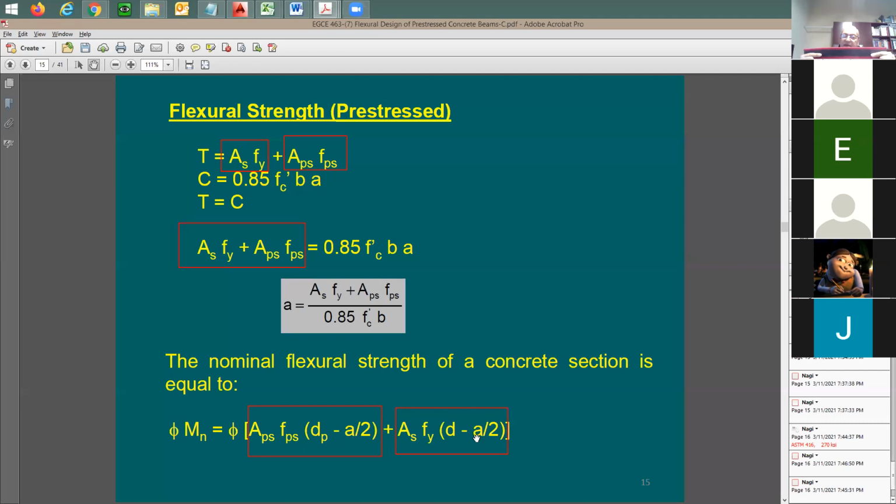So we're going to bring the beam, put it in place, put some conventional rebars, enough to support the self weight of the beam. And then after we put the concrete, we're going to wait a week and then remove the formwork. Now the beam needs to support itself, and it has enough reinforcing bars to support itself. And then after that, we apply the post tension to it, and then you apply the loads.